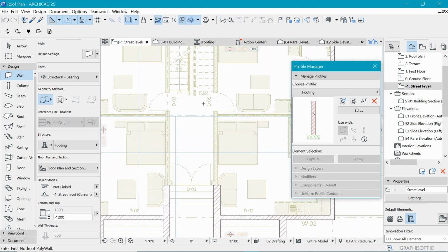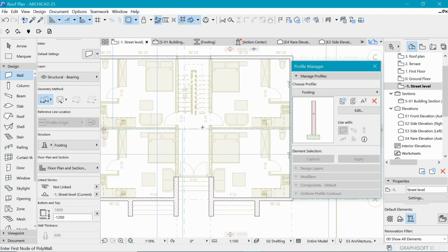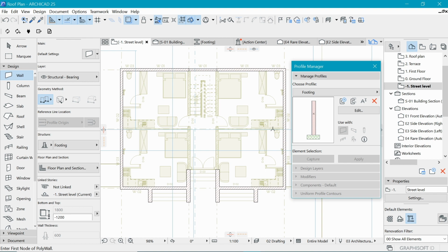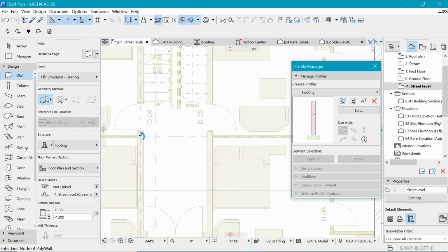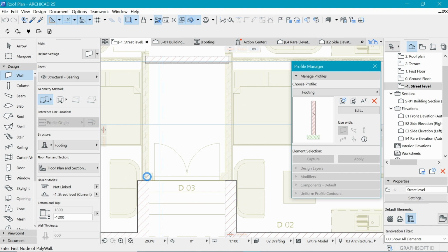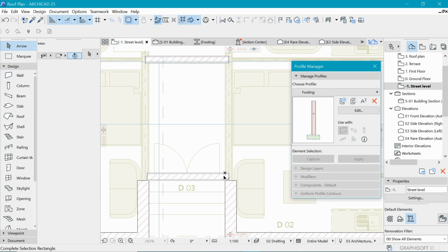Okay, and then we also need to identify, and I think since we have a partition wall in this area, we also need to carry that load to the ground, so we will have it here as well. So I will draw just that, and then finally we have this area here where we have the entrance, so it will also require us to have that in this area.